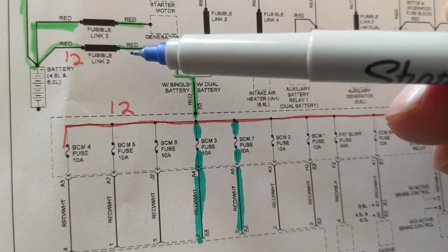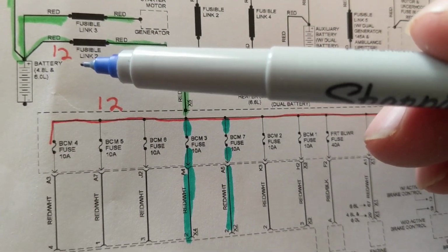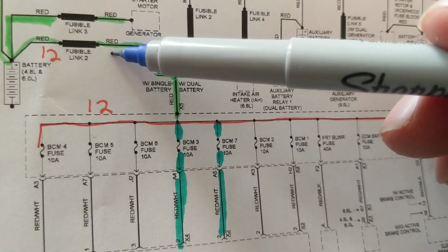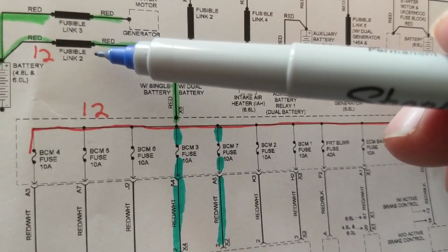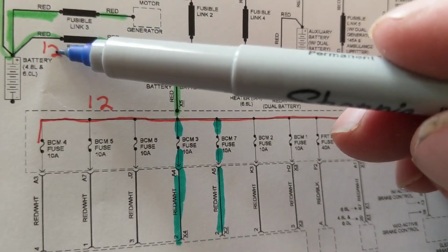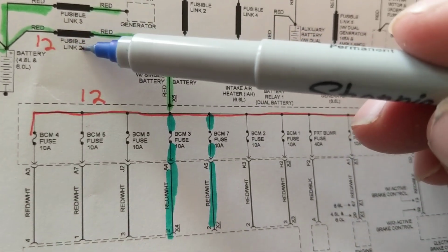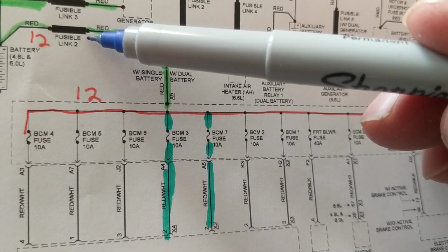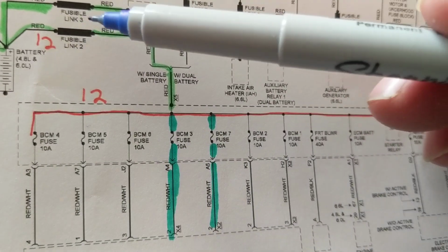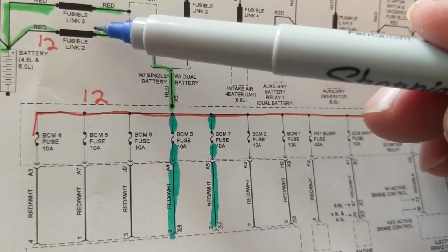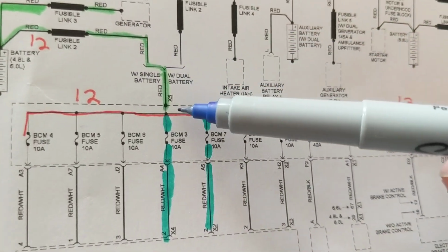With respect to 2 points, the voltage will be 12 here, 12 here. If this was 12 and this was 10 volts, that means we just lost 2 volts across this component. If this was 12 and this was 5 volts, we lost 7 volts across this component. So if this is 12 volts and this is 12 volts, we lost 0, or maybe 0.1, 0.2, which is negligible. We consider it 12.